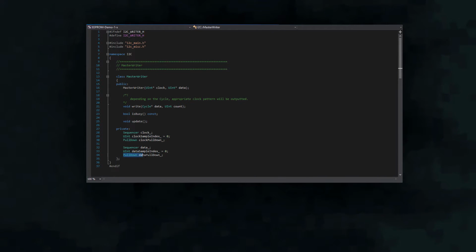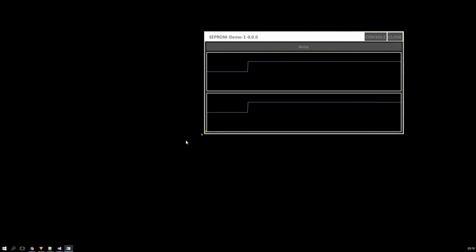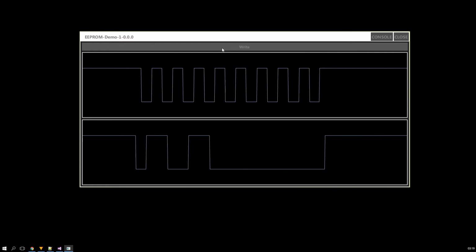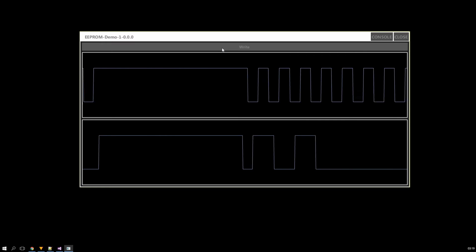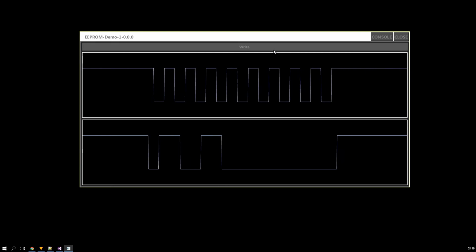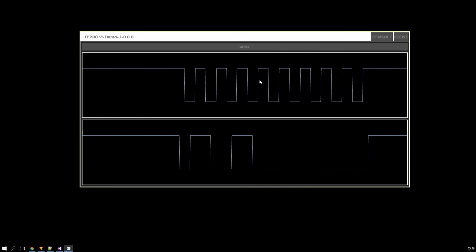So instead I'll capture the signal in the software right before I'd normally send it out to the pins and print its value to this UI component. I'd send the clock signal to the top one and the data line to the bottom. So this is the test user interface with the 2 signal monitors. Right now they're not connected to anything in the real world, no GPIOs or anything. They simply output whatever value is on the integer pull-down reference counter things. And it would have been clever to have a stop button. I'm gonna have to do this with a good old print button.